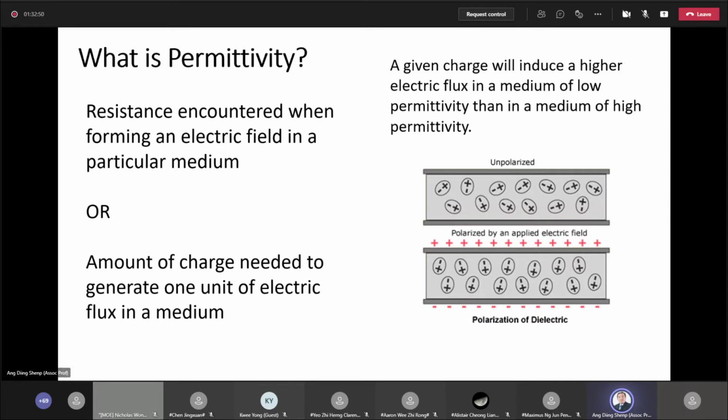Since gallium and arsenic have different electronegativity, if you form a compound with 2 elements of different electronegativity, there will be non-equal sharing of charge, because one element tends to like electrons more than the other. As a result of this difference in electronegativity, the gallium arsenide molecule is polar. In other words, one part of the molecule is slightly positive with respect to the other.